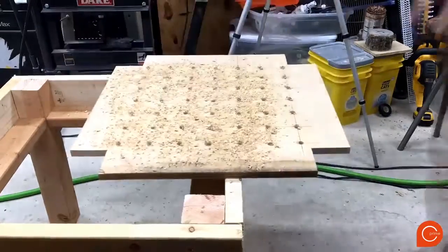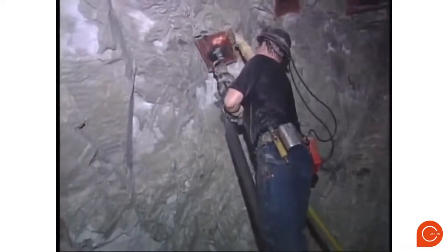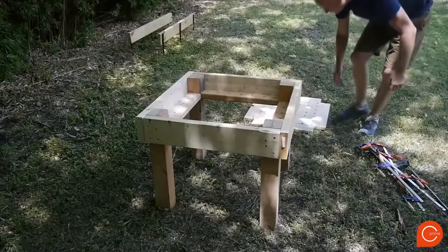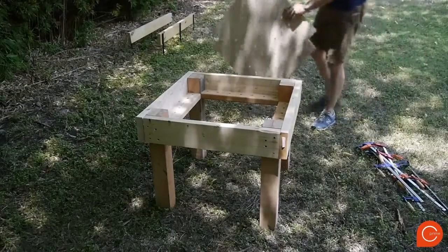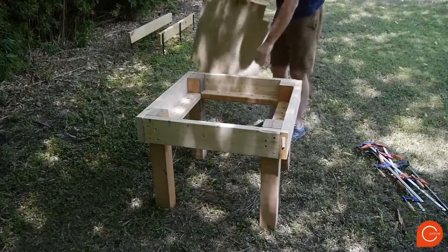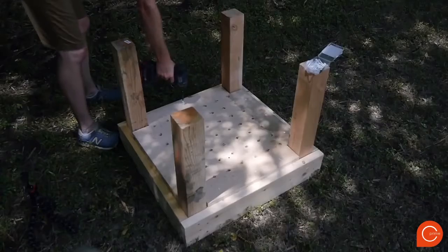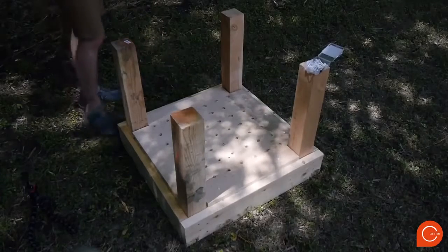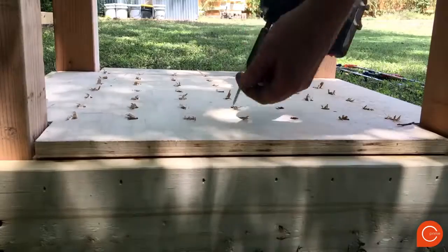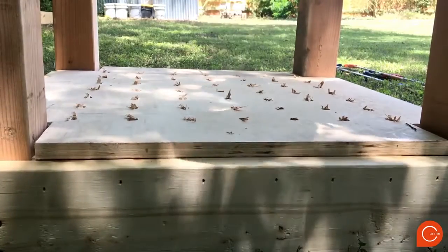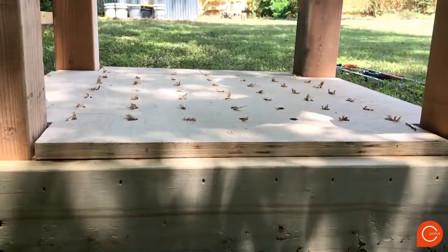Rock bolts are a type of reinforcement for stabilizing rock excavations, usually made from steel bars or bolts. I built this demonstration to show how they work. This is essentially the frame of a table, but the top is completely open. I attached a bottom to the frame to represent temporary shoring of a tunnel roof. Even though our permanent support system doesn't rely on this, it's necessary until we get the rock bolts installed.